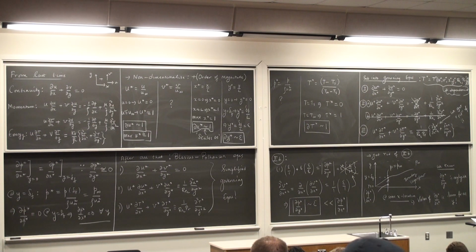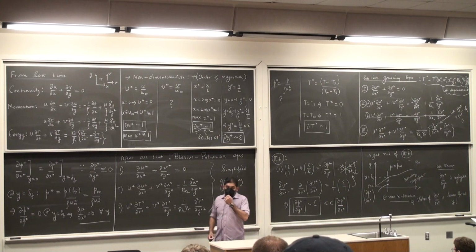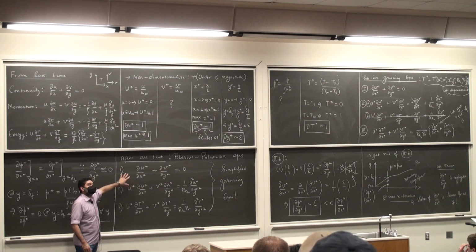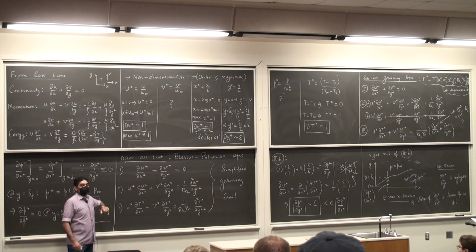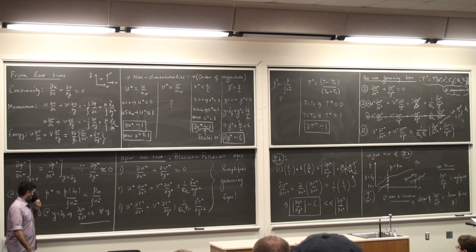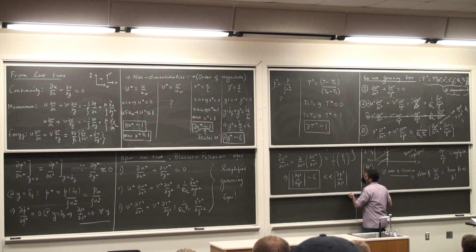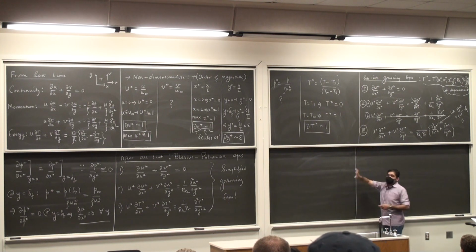Paul Blasius was a student of Ludwig Prandtl a long time back, and both of them are instrumental in essentially aerodynamics taking place to the extent that we have it today. The Blasius equations are the first two. Pohlhausen equation is the third one. In combination, they will help you solve for the boundary layer thickness, the first two. The third one will give you the convection heat transfer coefficient. Okay? And I'm just going to sketch out the solution procedure. I'm not going to go over the details of it. Until now, we have not been spared the gory details. Now I'm going to spare you some.